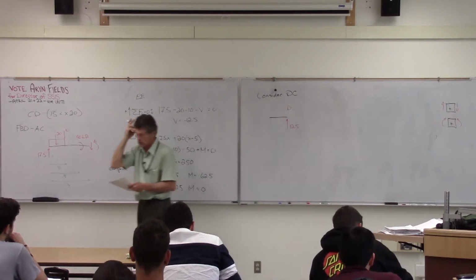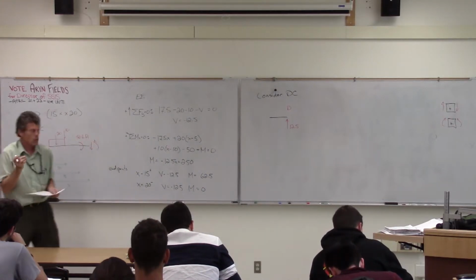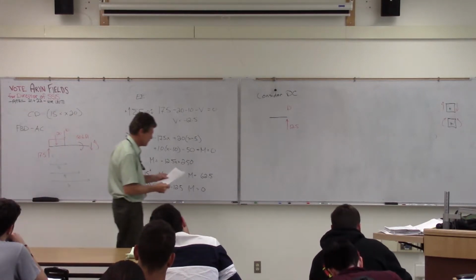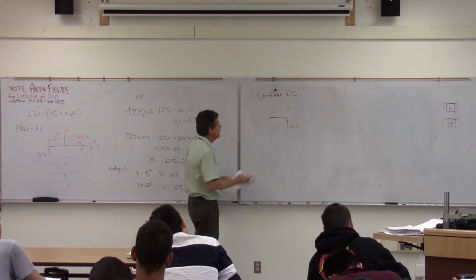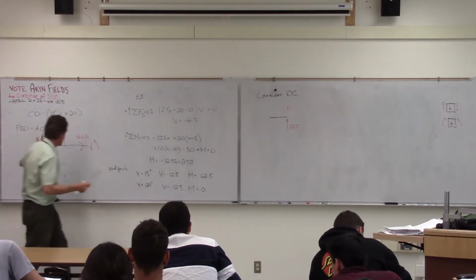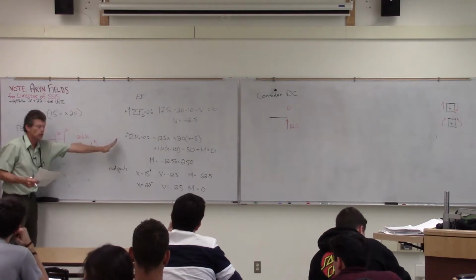What I find is that there's a concentrated force due to the reaction at that end of 12.5. Now, when I look at this free body diagram, none of these forces appear to it because I'm making a cut here and looking this way now.